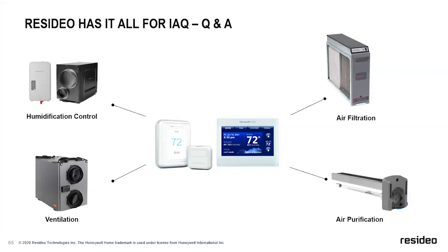And now you have essentially a much higher MERV filter that actually will protect the people in the home versus just a 1-inch filter that's designed just to protect the equipment. So that's the whole purpose behind those filter grill filters. Exactly. Yeah. So no, like you said, no duct modifications, but you're getting more surface area on the filter.